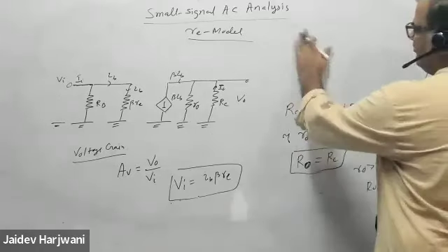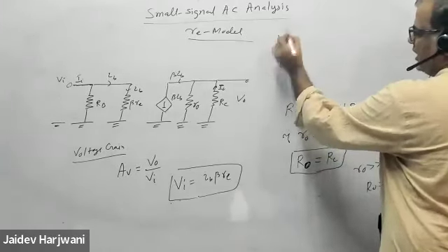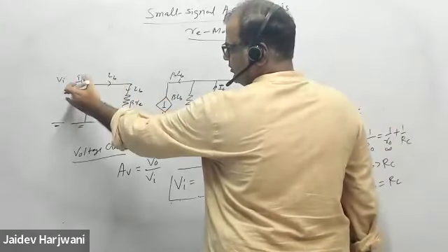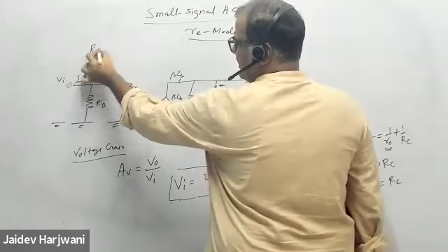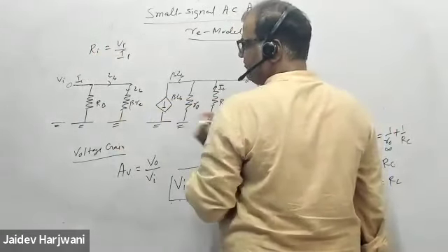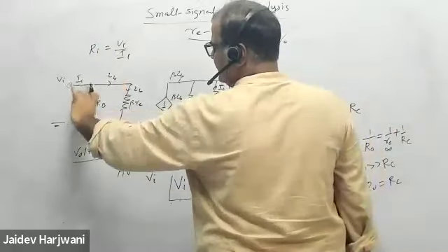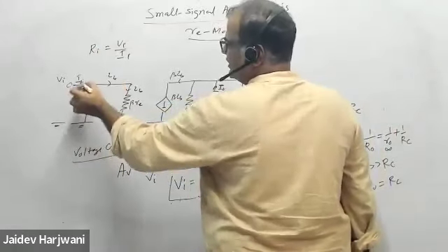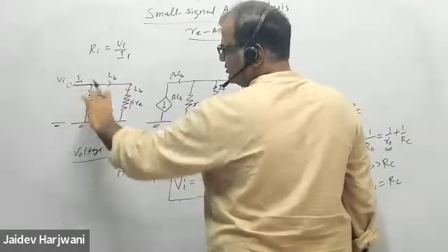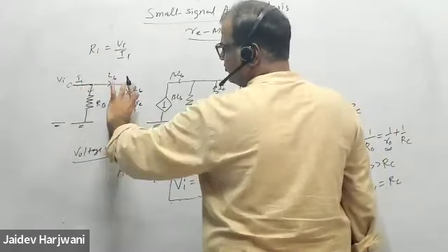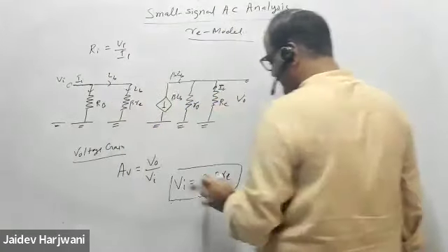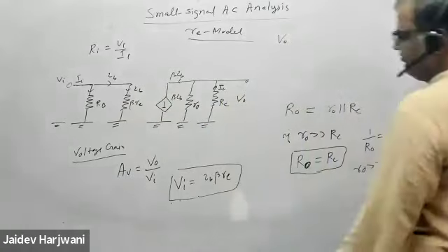If I want the total current, I want VI, but if I want simply VI, that will be this. This is the total current, this much is going here, and how much goes here we can also find. Either this voltage or this voltage, so I know this current directly. So I can directly write IB beta RE, and IB beta RE is my V input.